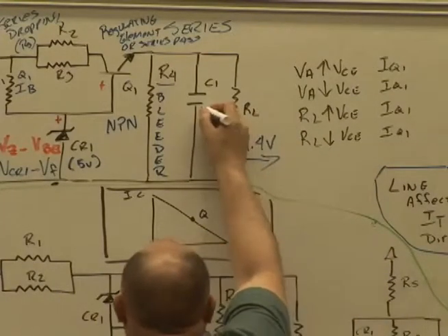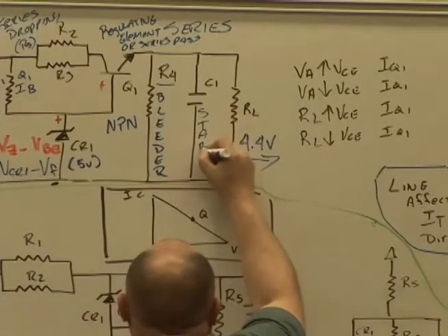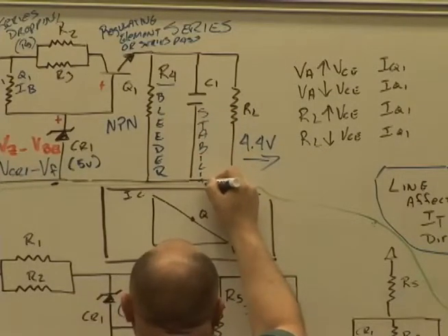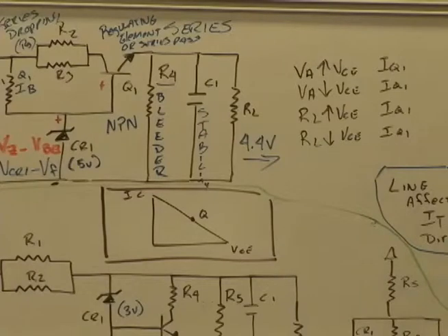C1, all these capacitors, just think stability. Whenever you see something like unwanted transistor oscillations, shunting AC variations to ground, that's what all these capacitors do in every one of these circuits. And of course, we've got the load itself, which represents whatever I'm plugging into the circuit, like the gyro model. That's the load.